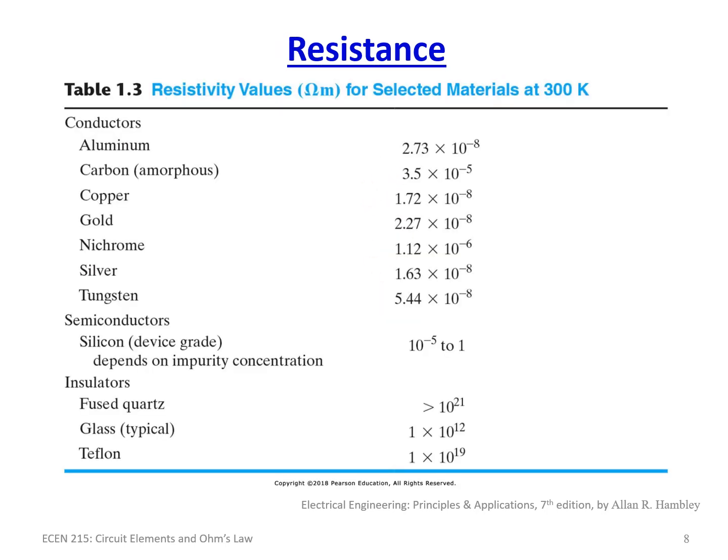Which brings us to resistance tables of all the different types of conductors that are out there, and there's a whole lot of these, and you can determine the rho, if you will, the ohms per meter for all sorts of different conductors: aluminum, carbon, copper, gold, for instance, silver, tungsten. So as you can tell, gold is very ideal, and it's heavily used in a lot of circuits, actually gold plated. And obviously things like Teflon and glass, times 10 to the 19 ohms, are ideal insulators.